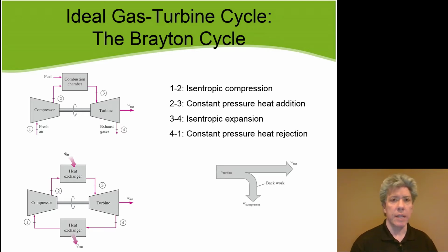Now, one thing about this, if you notice, the compressor is back driven by the turbine. Just like in the Otto or the diesel cycle, when the piston compresses the gases before burning fuel, that takes energy, that takes work. So in the same way, the compressor also requires work in order to operate, and that has to come from the work-producing device, which is the turbine.